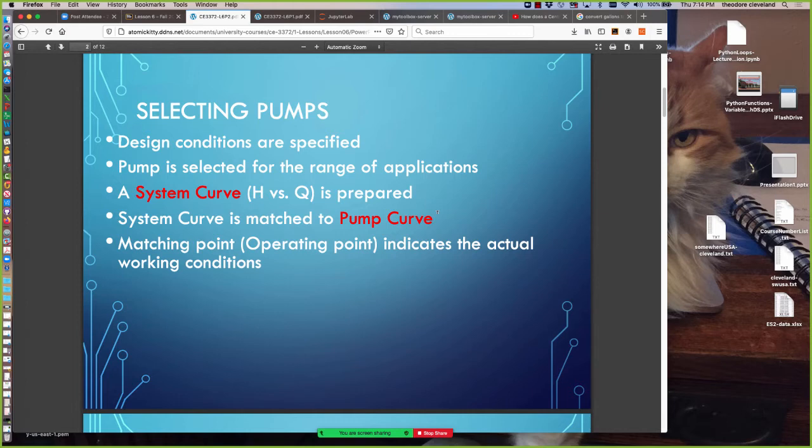By that, the network we're going to attach the pump to, and we specify design flows, a lower flow and a higher flow. And to come up with those, that's when we do that what if analysis. What if the valve is left open? What if the pipe breaks? What if the float valve fails? So that was what we visited last time in class.